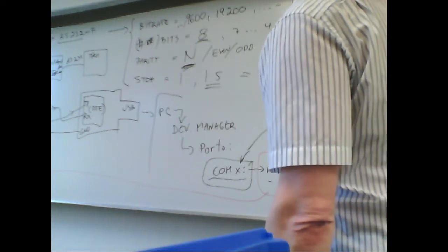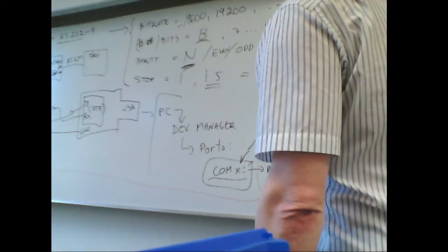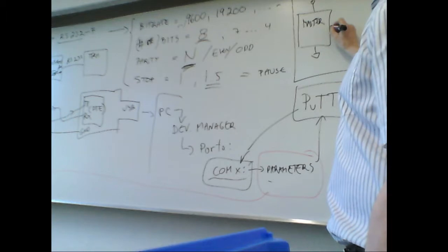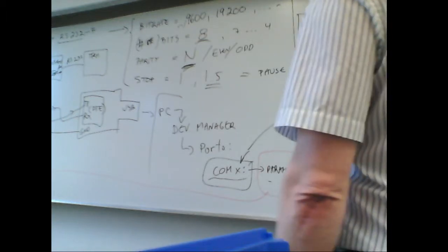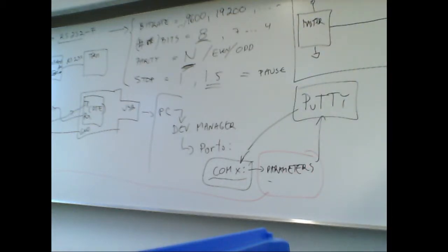Okay, here we have the master device, which is powered normally. Then it has this one wire line going to the device. The one wire means that you can actually power it up also from this line directly. You do not need necessarily to power this one from any external power supply. But since that is available, why not use it?